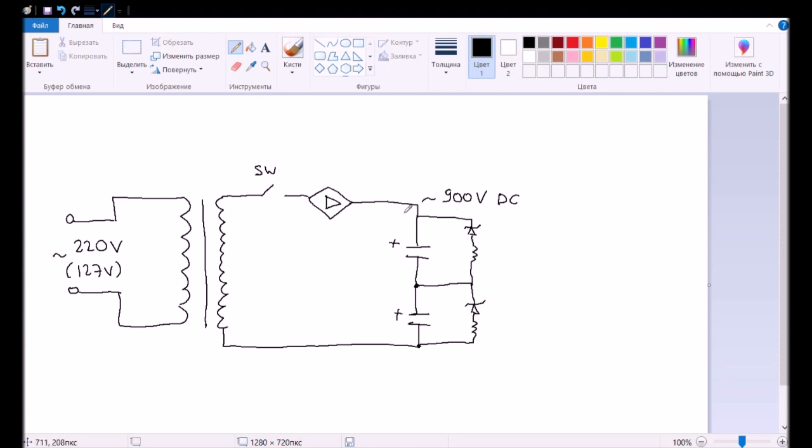So the disadvantage is very high power losses here. And if we try to charge not a single block of such capacitors, but for example a coil gun with many stages, we must provide all these blocks with according circuits, and it is a very complicated structure. Very complicated and very inefficient, because heat losses are very high in each stage. So what should we do?